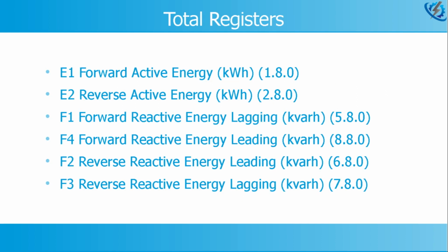Totals are your monthly totals that can be used to calculate bills on basic tariffs such as inclined block tariff. You typically only need one total at the start of each month, however there can be many totals read during a month. There are 6 totals that we read. E1, or forward active energy. This is the main total that most people know of, measured in kilowatt-hour.